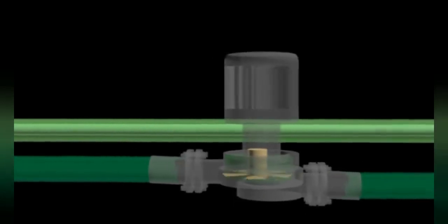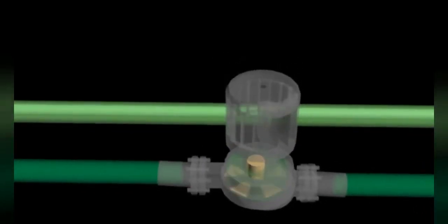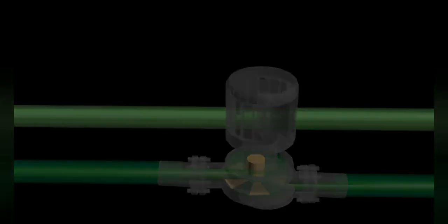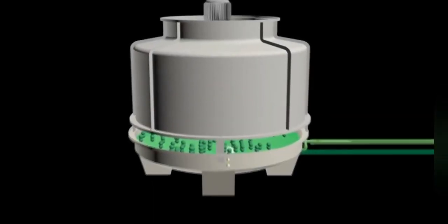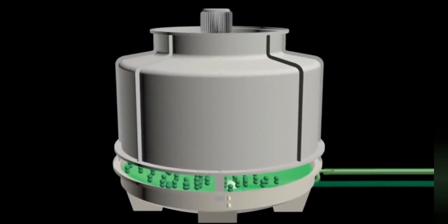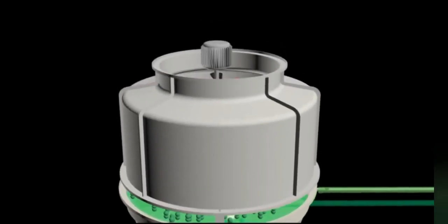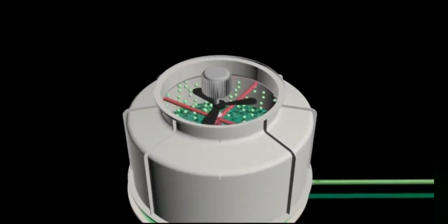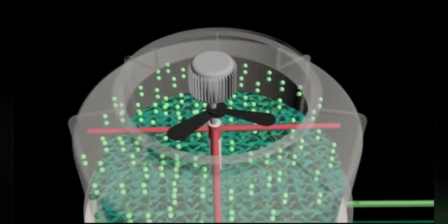From the condenser in the chiller, condenser water flows to the cooling tower with the help of a centrifugal pump. This water is called condenser water return. This condenser water will pass through the rotating sprinkler blades on the cooling tower. These rotor blades rotate using pressure generated by the condenser water itself.